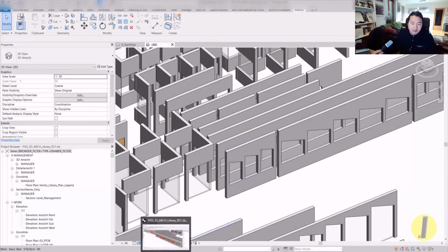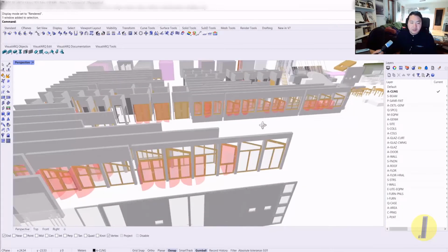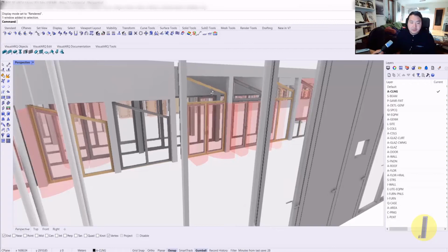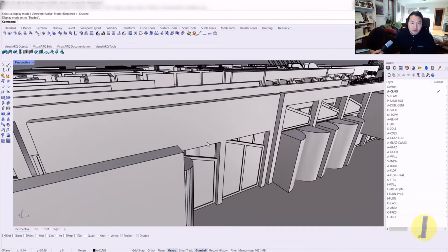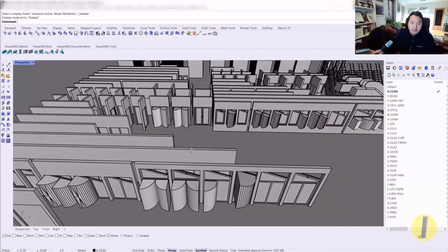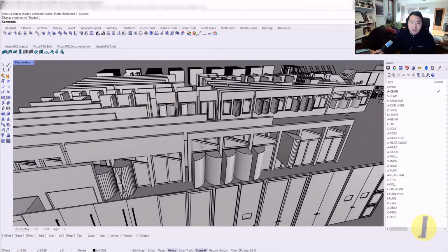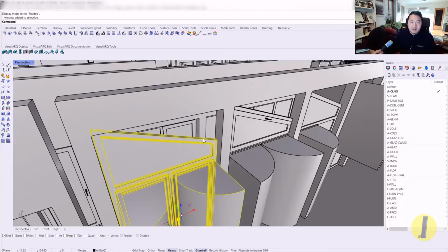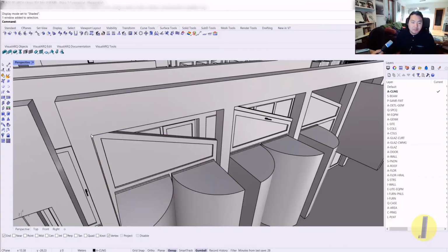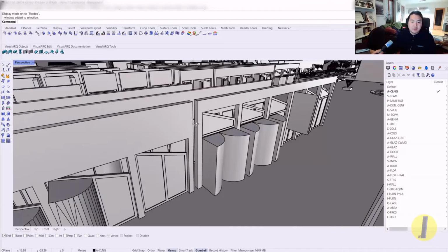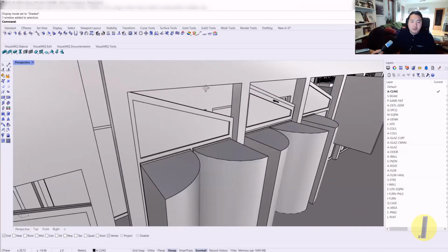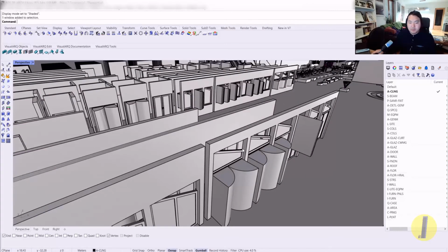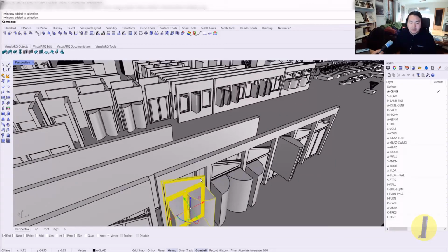That's why maybe they show different geometry, but some of the openings for the polygonal ones are all wrong, which is a bit disappointing for me, because I think visualARQ doesn't have polygonal openings. I always had difficulty working with polygonal openings, so I always use Boolean difference to make openings in the wall instead of using a window or door opening.